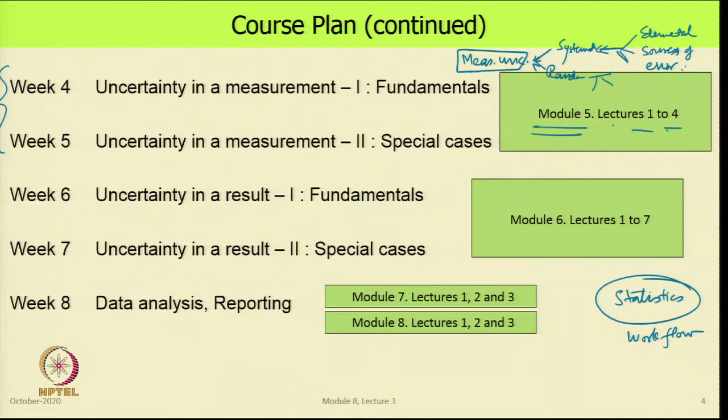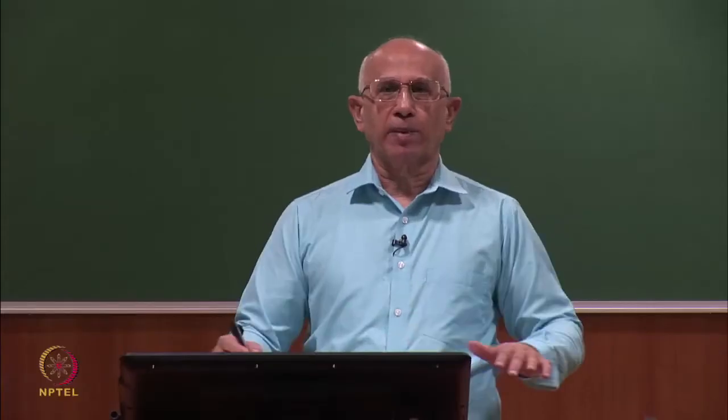As many measurements are there in an experiment, that many of these analyses have to be done. So, at the end of this, we have a measured value, what we call a nominal value, plus minus certain uncertainty at a certain confidence level. So, these are things we got. That was all the data that we wanted from the experiment.